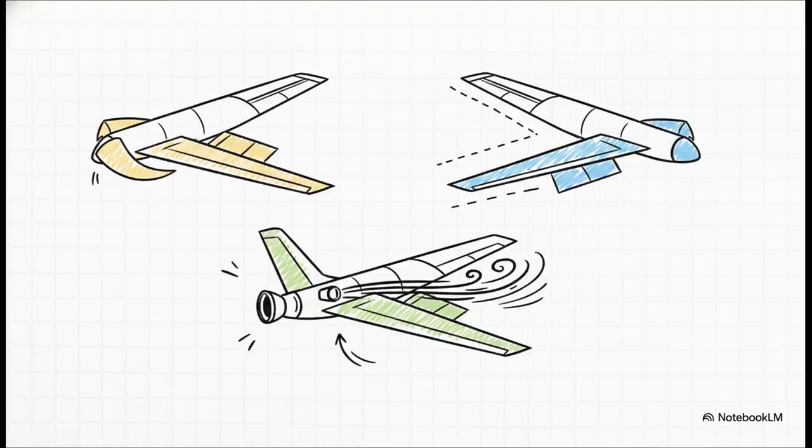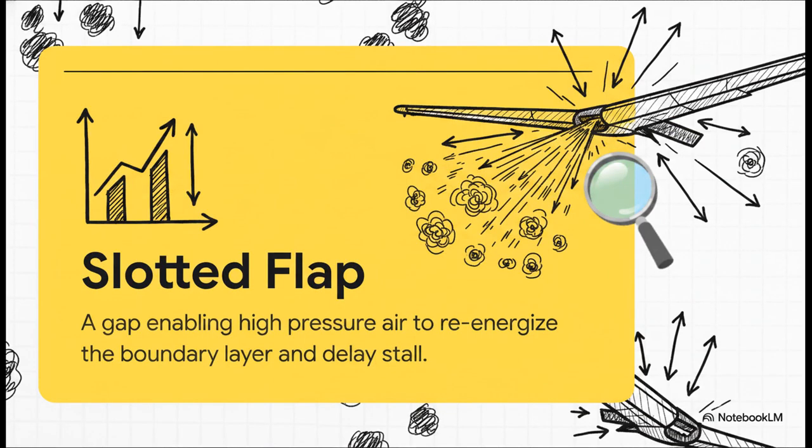And aerodynamicists have come up with some brilliant variations to maximize this effect. You've got Kruger flaps, which actually extend out from the leading edge or the front of the wing on high-speed jets. Then there are Fowler flaps, which are super cool because they slide backward before they hinge down, so they don't just add curve, they increase the total surface area of the wing itself. And there are even blown flaps, which actively blow engine air right over the wing to cheat physics and create even more lift. But honestly, the sheer ingenuity of the slotted flap is amazing.